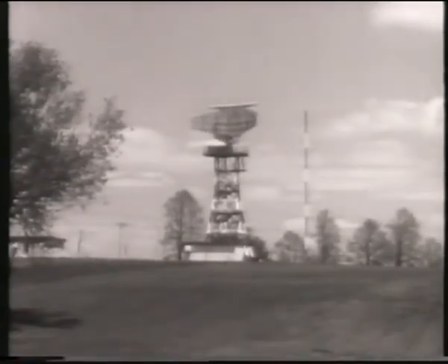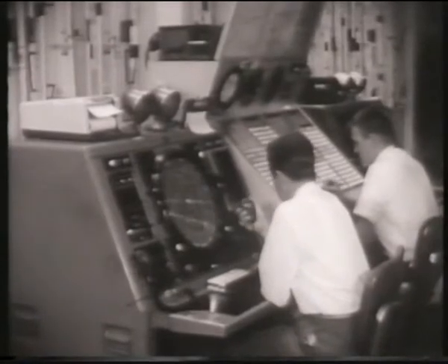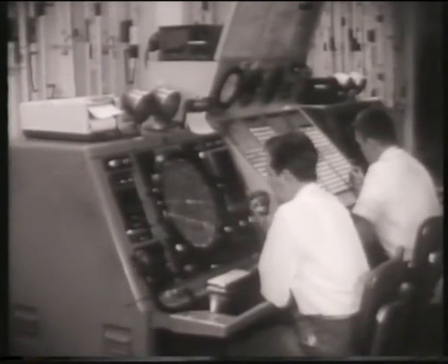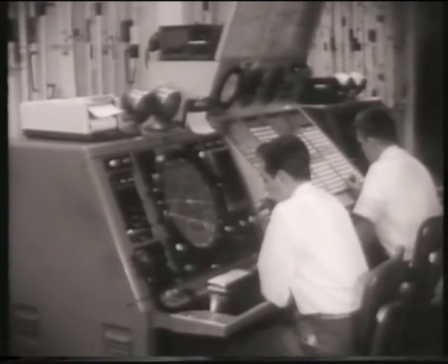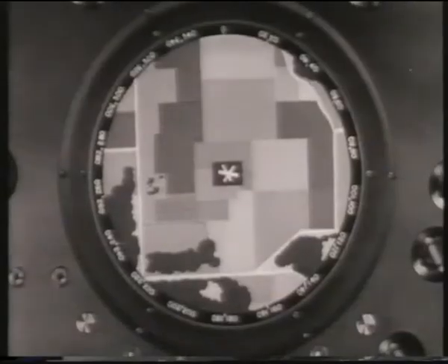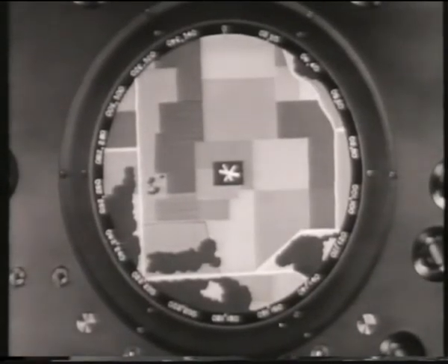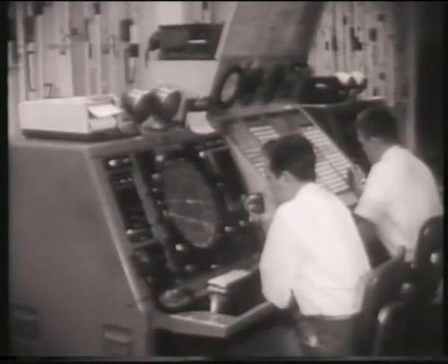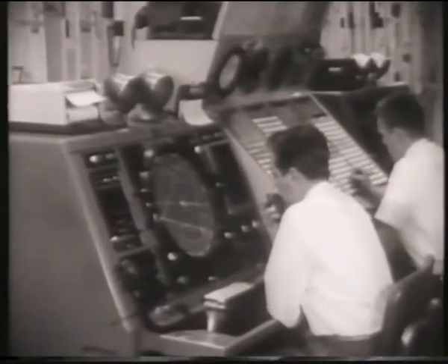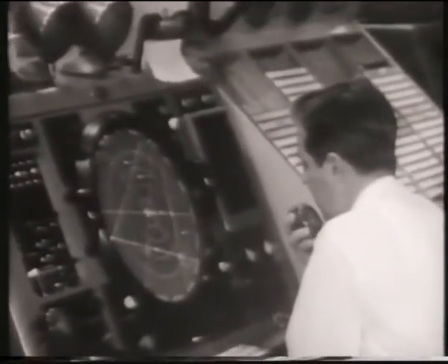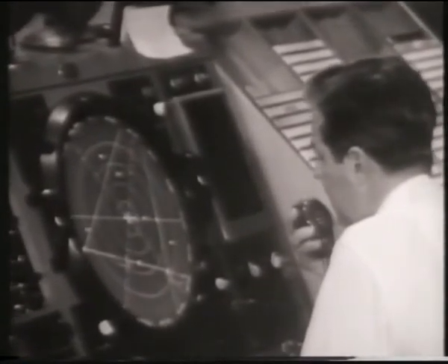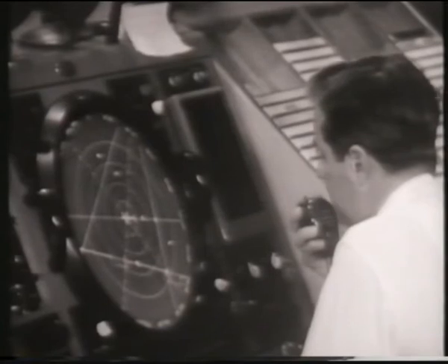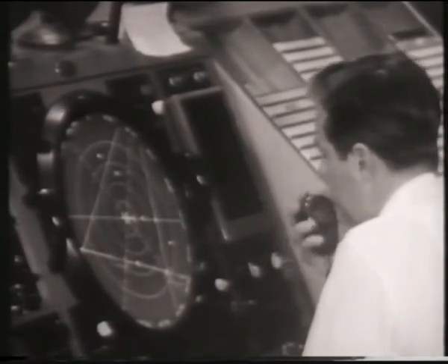Surveillance radar equipment used at busy aerodromes and along some air routes helps air traffic controllers to detect, identify, and direct the movements of aircraft traffic. Controllers see aircraft in the 360-degree area covered by SRE scopes as moving spots of light, each representing an aircraft to be controlled. Radio telephone is used to give pilots control instructions and headings to fly, which guide their aircraft into and out of aerodromes and along air routes safely with a minimum of delay.